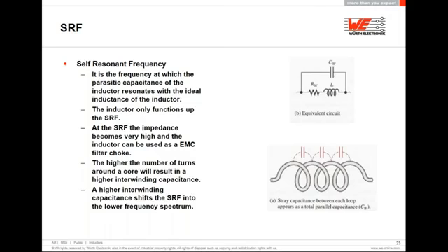Keep in mind that a higher number of turns around a core will result in a higher inner winding capacitance. Therefore, this shifts the self-resonant frequency into the lower frequency spectrum.